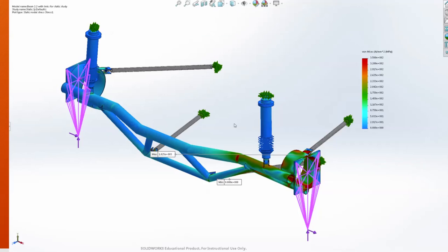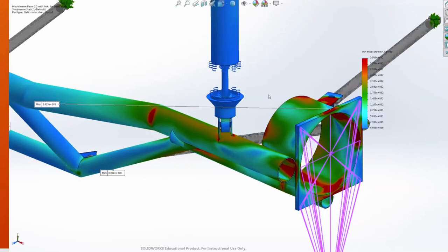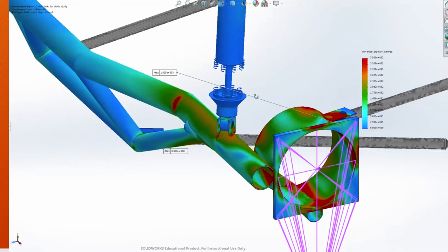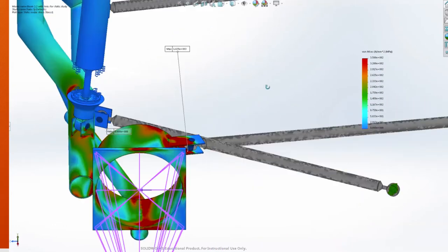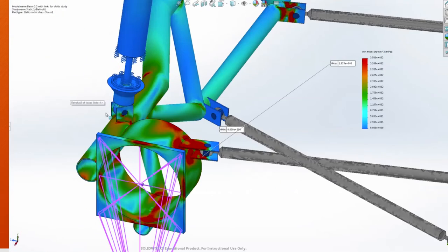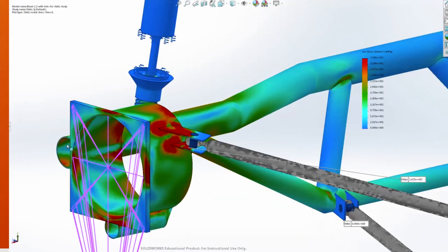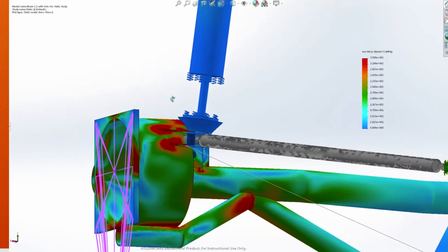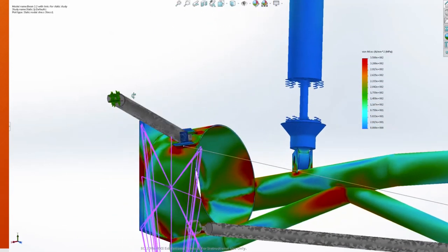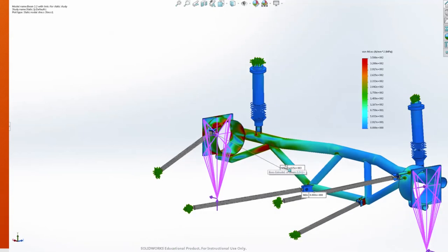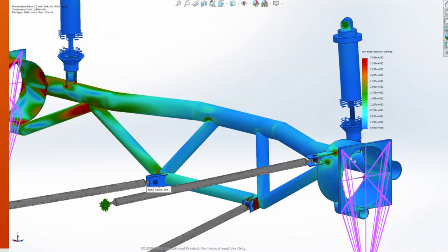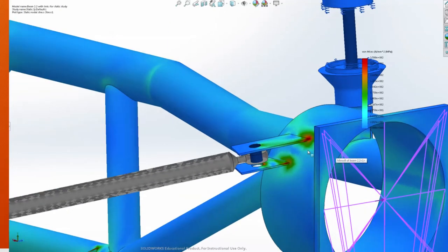This is a more promising style of beam we came up with. It is a truss style. As we can see, there are more stress concentrations than in the original beam. However, more of the beam is green than blue. More of this material is being stressed, and the same loads that the original beam had are being distributed to more material. So as you can see, we predict a lot of failure here with the same loads and the same type of steel with a 350 megapascal failure.